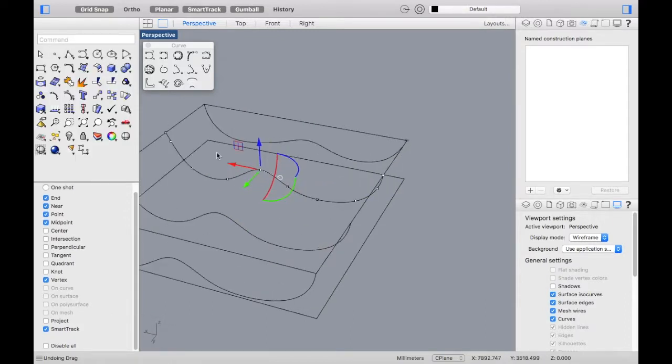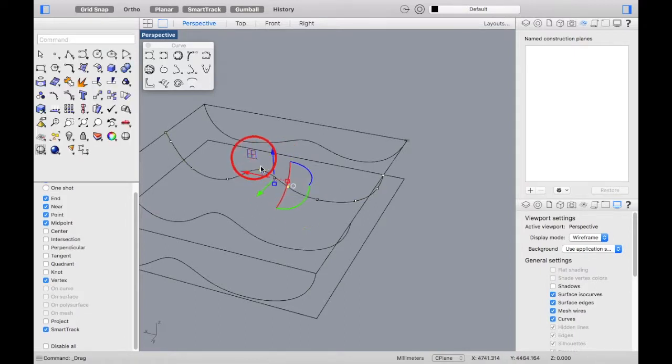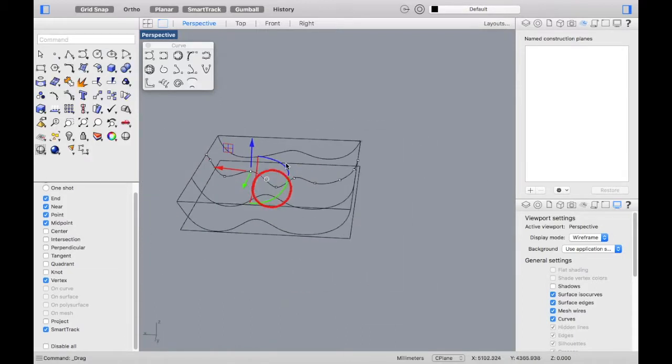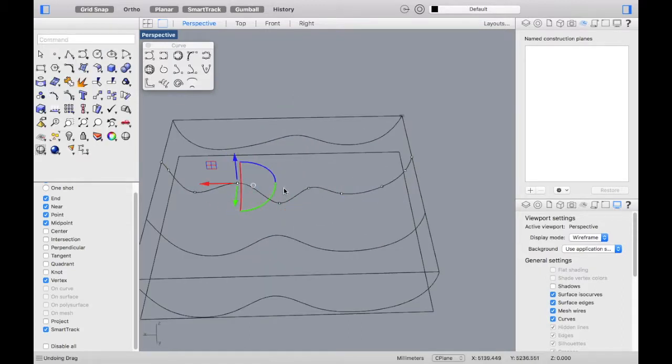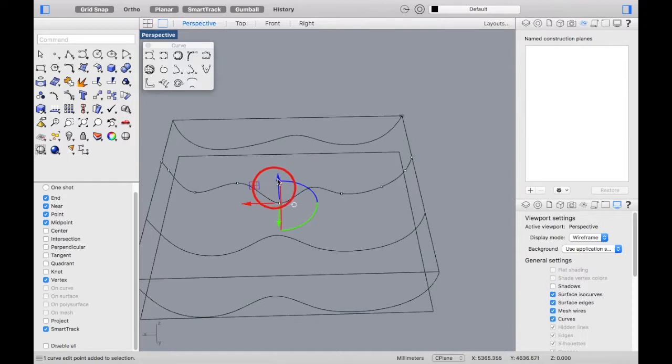But make sure if you are working with a certain constraint of height, then that's why I created another base at the bottom, to know that that is my constraint and I cannot move beyond that. This is my height restriction. So for this you need to turn your gumball on. I have another video in which I run you through the basic commands on Rhino, which I basically use mostly.